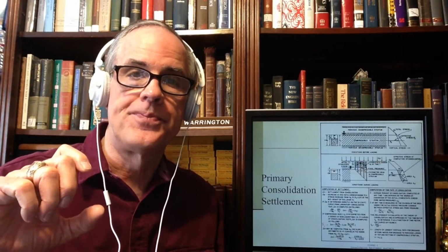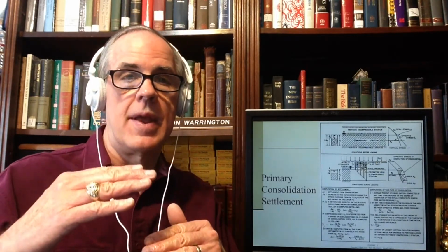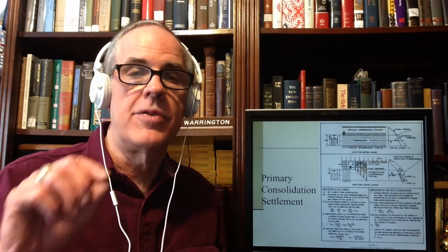The center of the layer, usually we have the average, and that's where your average effective stress is. And this is something that students kind of get stumped on, because the initial stress of the layer is the average effective stress before anything else is applied to it. And then from there it settles. And delta P is the change that we actually induce, or whatever pressure we put on the top. And that pressure can be due to a number of factors, and we're going to look at how that works. P naught plus delta P is the old pressure plus the added pressure, which makes the new pressure in the middle of the layer. In the middle of the layer, average effective stress, average stress. That's what we're talking about. Not the one at the top, not the one at the bottom, the average.